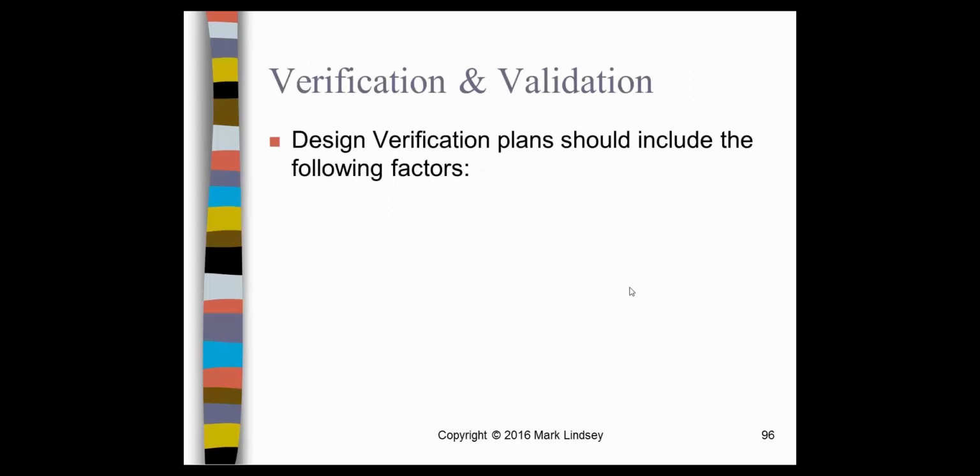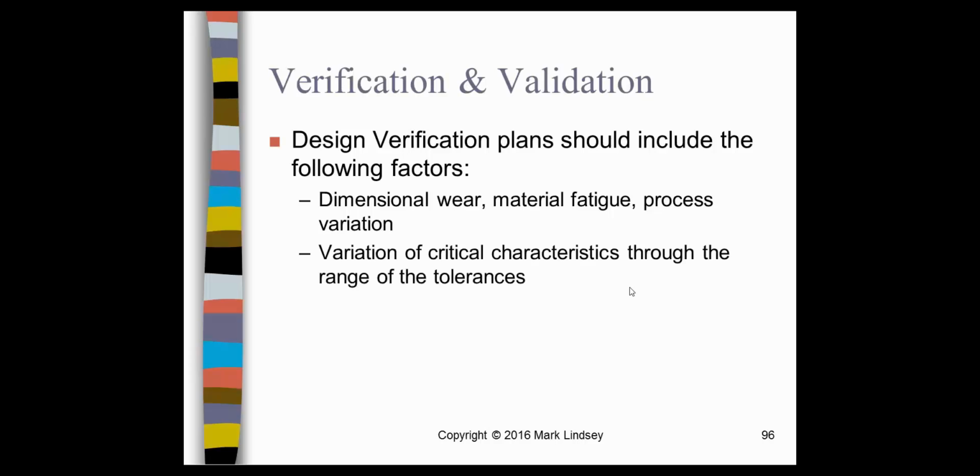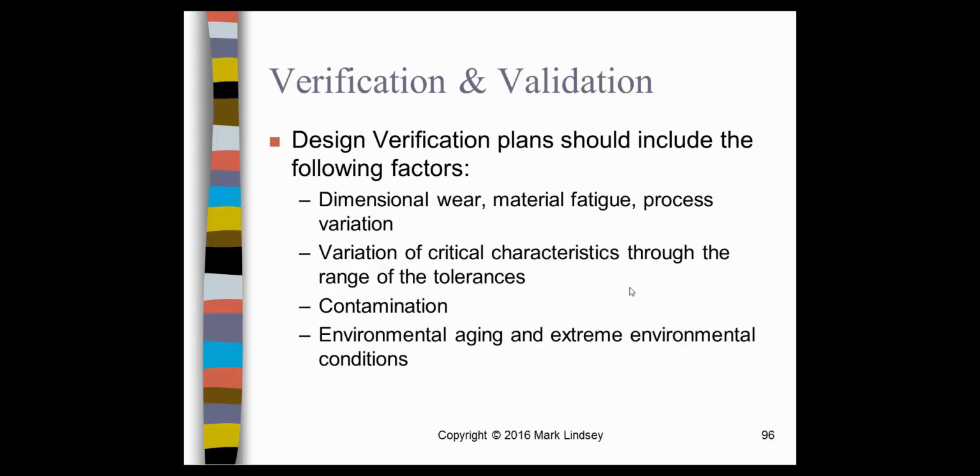So your verification plans should include the following factors: dimensional wear, material fatigue, process variation, variation of critical characteristics through the range of the tolerances, contamination, environmental aging, extreme environmental conditions, and these are all examples. Extreme customer usage.